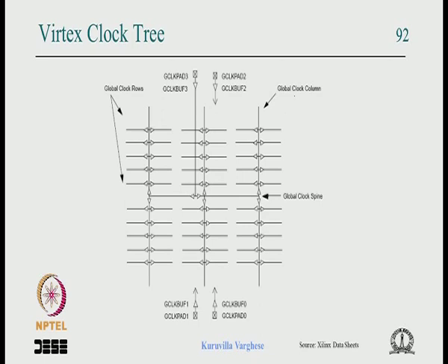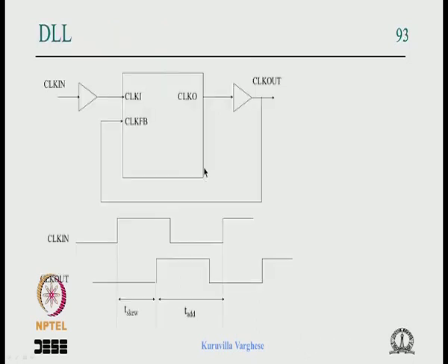Sometimes you need to clock by the user clock, or there is a clock limited to an area of the slice or CLB of the FPGA. That should be kept in mind. Whenever you want to use the dedicated clock pins, use the dedicated clock tree and so on.